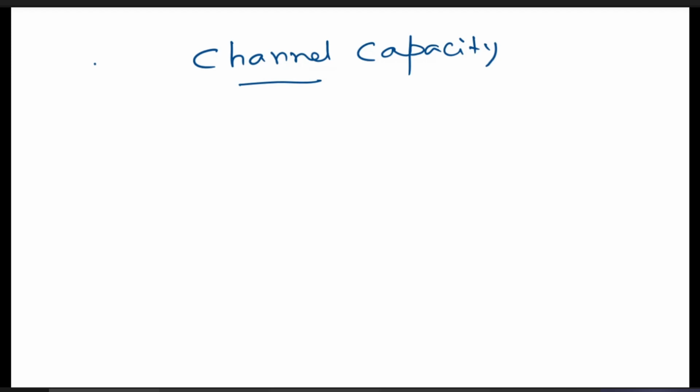Intermodulation noise is actually the generation of new frequencies because of nonlinearity. The nonlinearity may be in the transmitter or in the receiver, or maybe in between the channels. Some new or different frequencies will be generated because of this nonlinearity and excessive signal strength. So that is intermodulation noise. We'll see in different cases how these noises limit the performance. That is most important in intermodulation noise, even in multiplexing also.